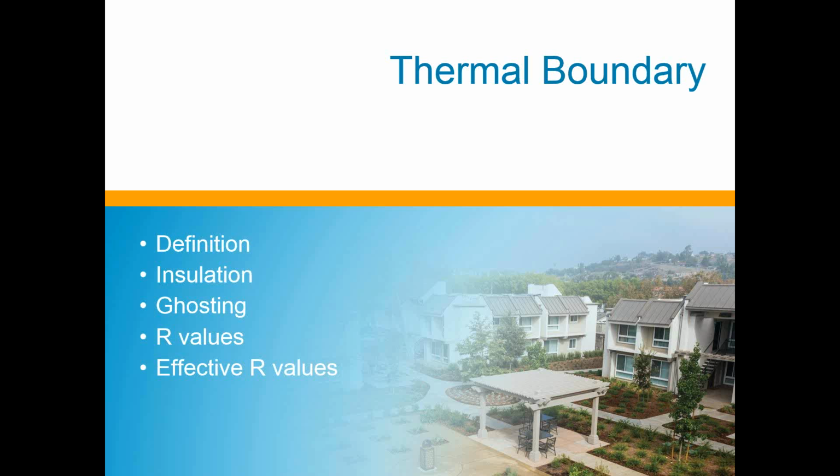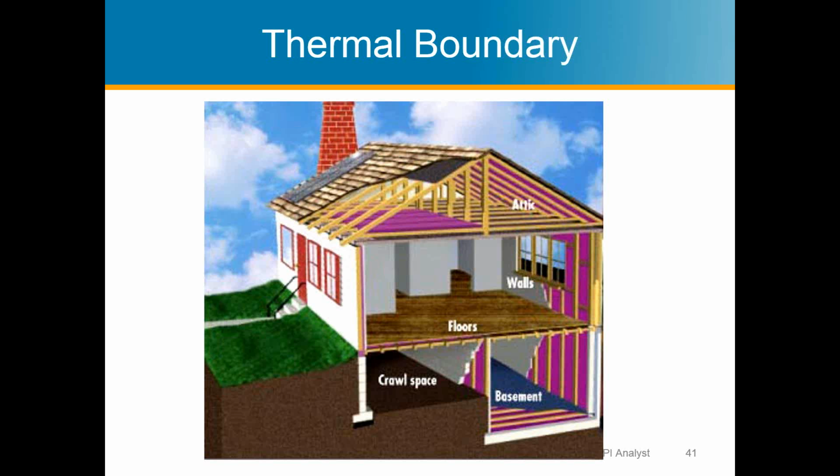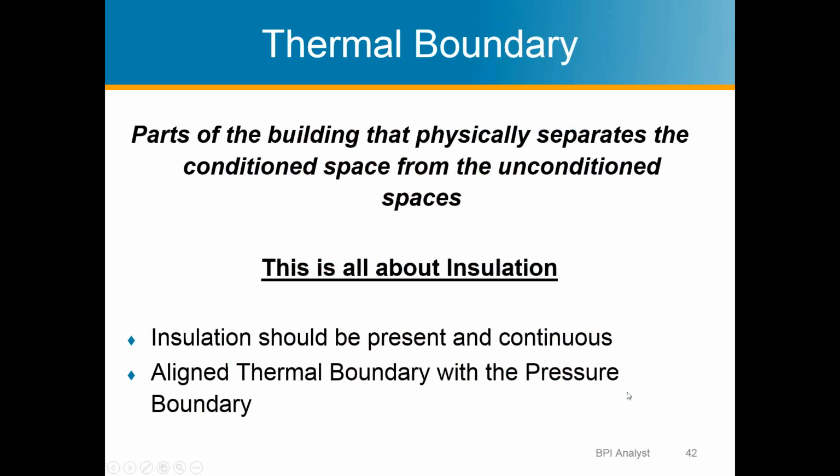All right, thermal boundary. Thermal boundary is all about insulation, so that's what this piece is going to be talking about, and where that thermal boundary is located. So like here, this picture has in the attic a thermal boundary at two different locations. On the left side, it's showing it in the ceiling, and the right side is showing it on the underside of the roof itself. And then like the crawl space area there, we got a thermal boundary in the crawl space that then goes down the wall and into the basement. But that's all thermal boundary issues.